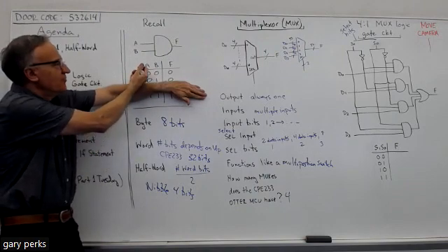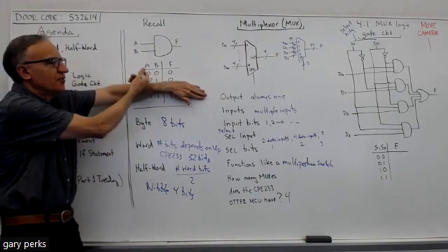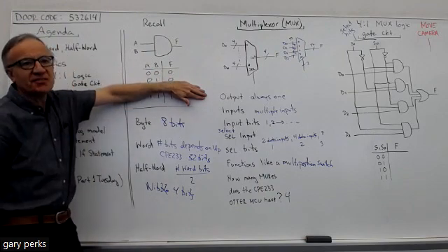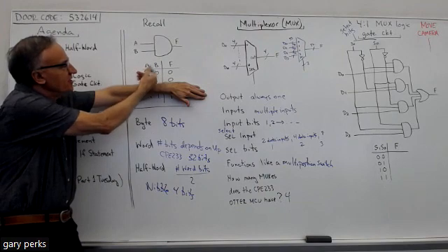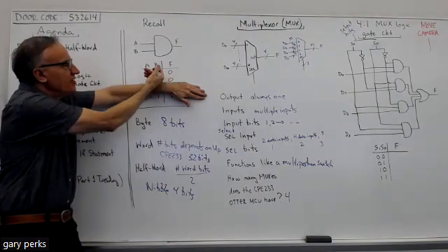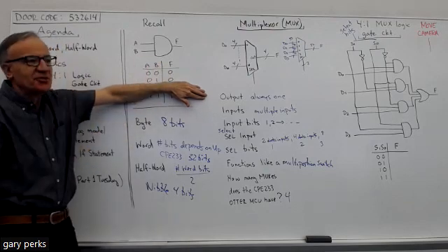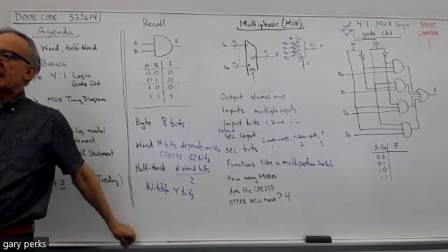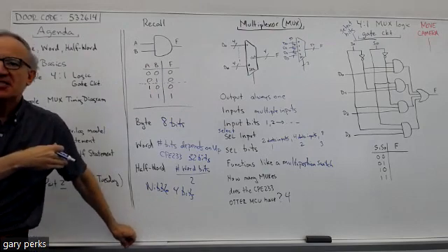Do you see what it's telling us? It's telling us that if one input to an AND gate is a 0, the output is 0 regardless what the other input is, right? Because if A is 0, the output is 0, and it doesn't matter what B is. If B is 0, B is 1, it's still an output of 0. So if I have a 0 at the input of an AND gate, I don't have to know what the other input is.